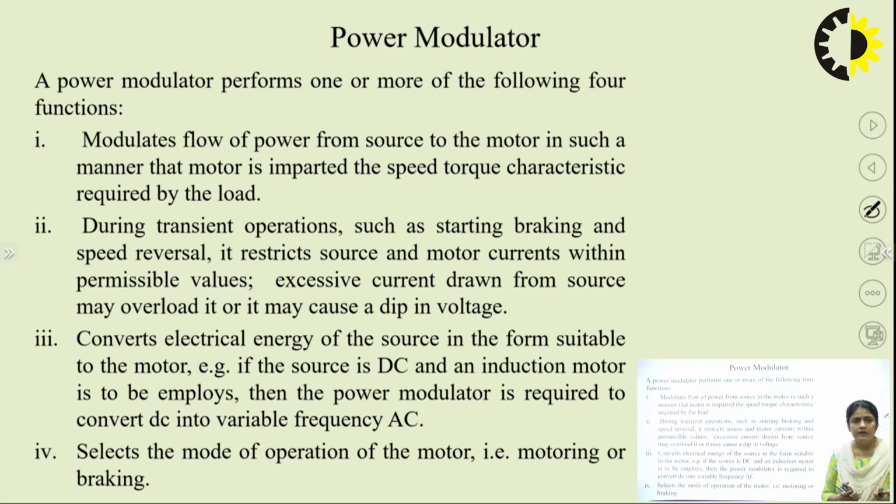And third, with the help of one block diagram, one electric drive system, we can perform 4 quadrant operation. Like we can perform the forward motoring operation, forward braking operation, reverse braking operation, and reverse motoring operation. So with the help of this power modulator, we are able to do this kind of operation with one arrangement, one electric drive system, right?